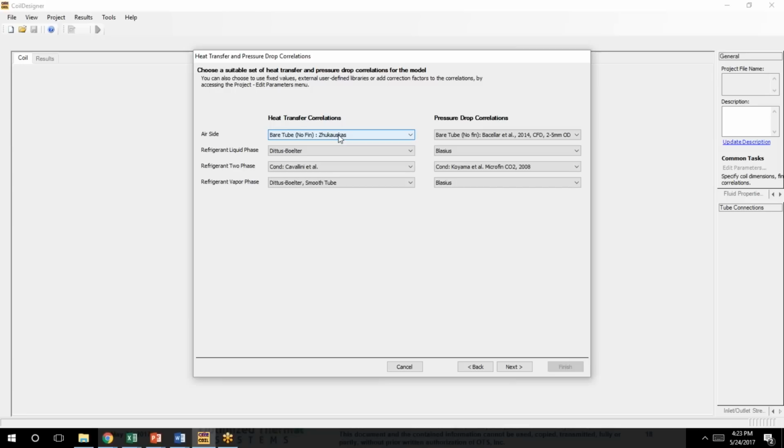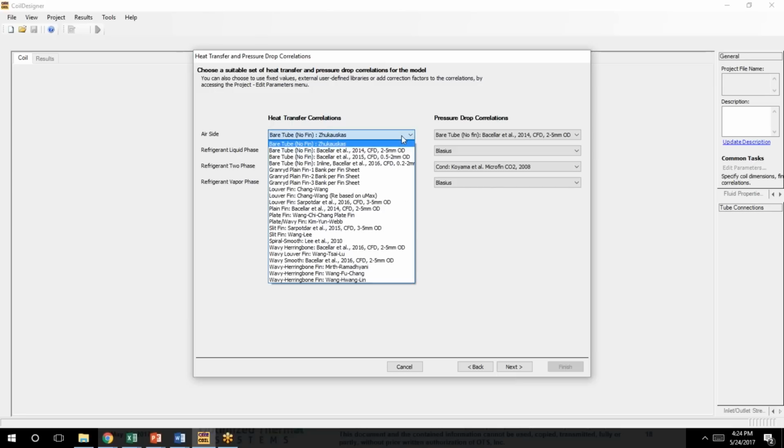So as we covered before in the first webinar, the airside heat transfer is really fundamental in predicting overall heat transfer performance. It's definitely the dominant resistance in most cases. So it's crucial that we get the airside heat transfer coefficient accurately predicted. So we need to predict airside heat transfer coefficient for a louver fin, which is what we selected. So we need to select correlations for a louver fin. And we can see that there are several correlations available in the literature.